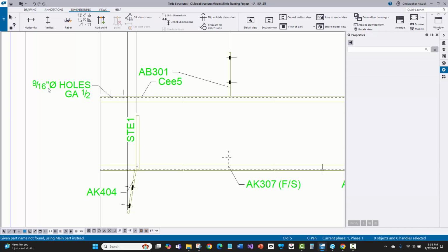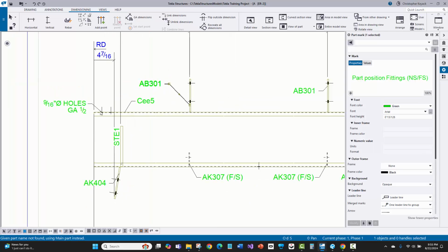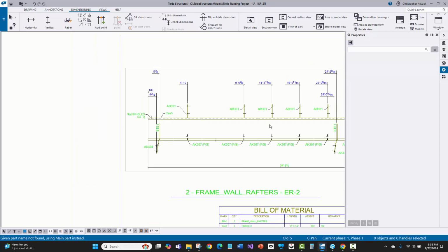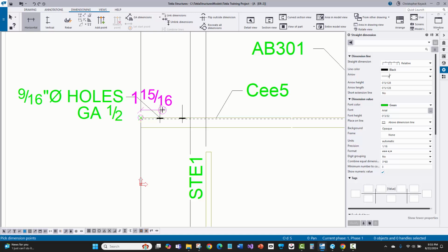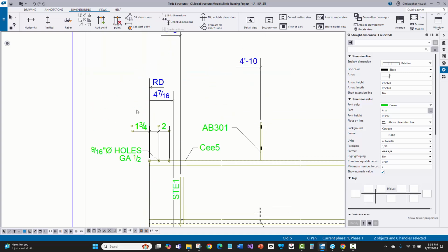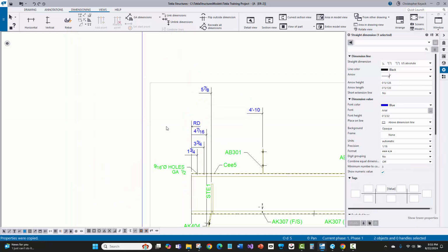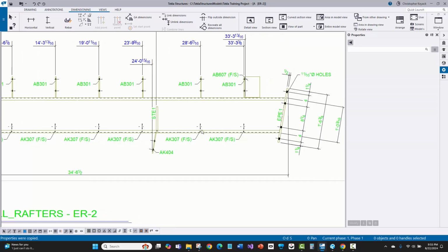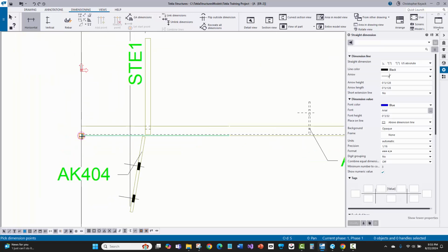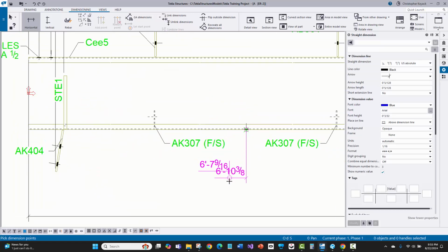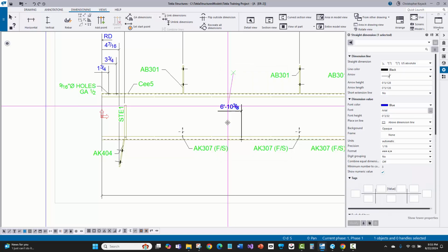And then now what I need to do is just add any additional dimensions or move things around. So here, again, because I've got the dimensions for the main part usually on hot rolled turned off, because I make single part drawings of that. If I do need those quick running dimensions, I can just add those, middle mouse button, and then those dimensions are there. Again, if I want to make those running dimensions, I select on this, use the paintbrush, select on this and modify. Okay, so there we can see those running dimensions. And then if there were any other dimensions on this piece, I could do that. Looks like I got one more here. So let me just do that on the bottom. Middle mouse button, and there we go. So we've got that dimension.